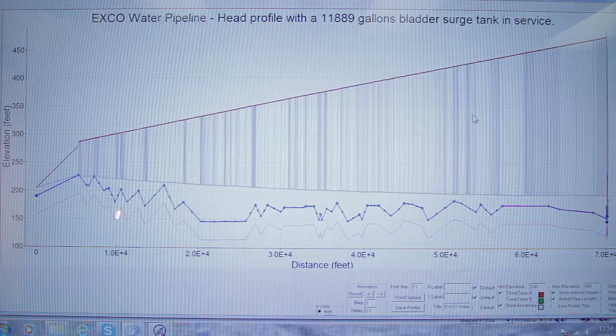And you can also see at the end the 2 points at the end, one of which I did show you, the air vacuum valve, where air is introduced at that point. Before, that transient wave was affecting the whole entire piping system, and the negative pressure wave would be allowing all those other air vacuum valves to open up and allow air into the piping. So you can see this is a well-balanced system, and at only 2 points at the end, we're allowing air to enter into the piping.